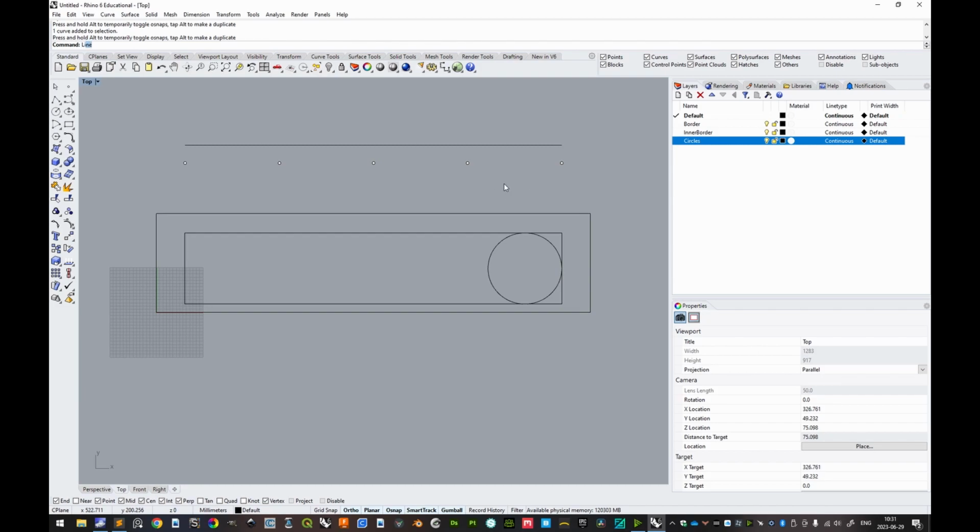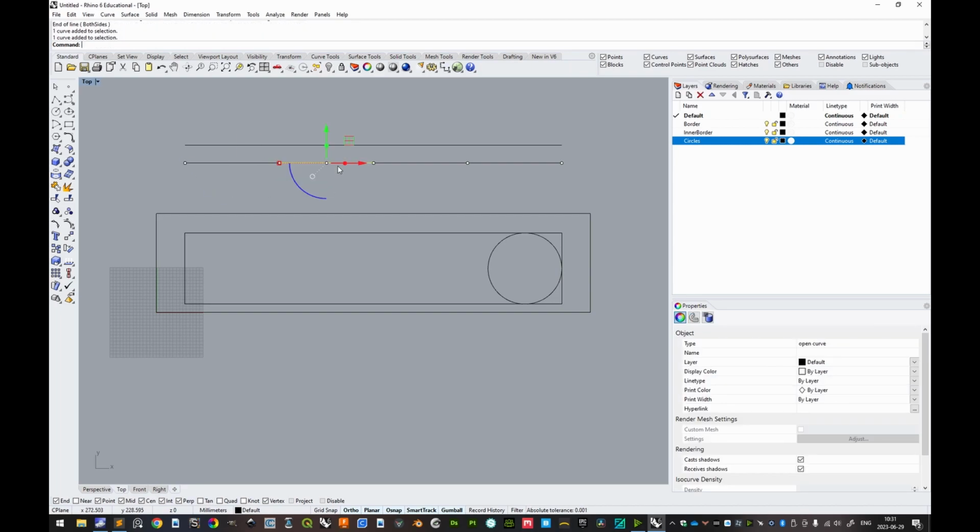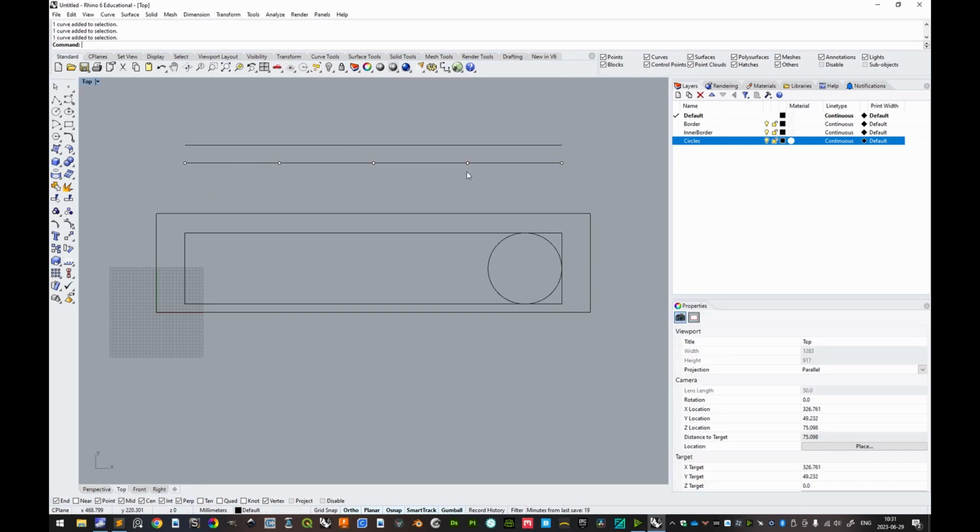And then we can actually do like this. We could move the line itself a little. And then we could create lines from point to point. If you click space, you'll repeat the lastly executed command. So having already created a line, I simply click space or enter as a matter. And then point to point and space again to do another line. Very good. Because now all of these lines have a midpoint of their own. There were only 4 to create, so it was quite simple.